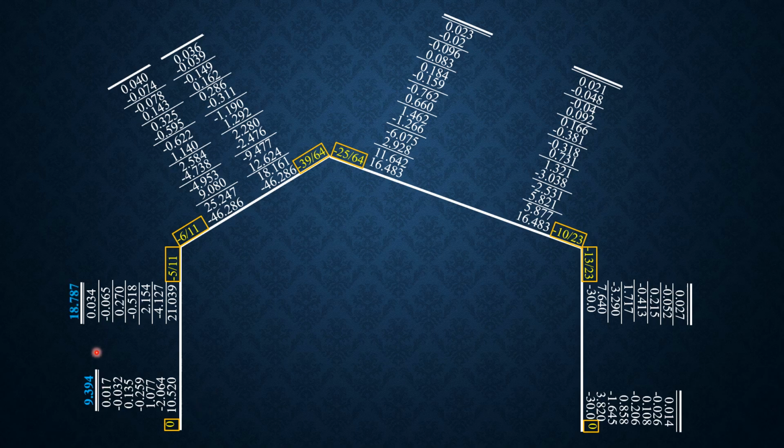Therefore, moment AB is the moment due to R1 from sidesway delta 1, which is in terms of R1, and these moments here are expressed in terms of R2. So moment AB is negative 31.415 R1 plus 9.394 R2. Moment BA is equal to negative 32.827 R1 plus 18.787 R2. Moment BC is equal to positive 32.827 R1 minus 18.787 R2.